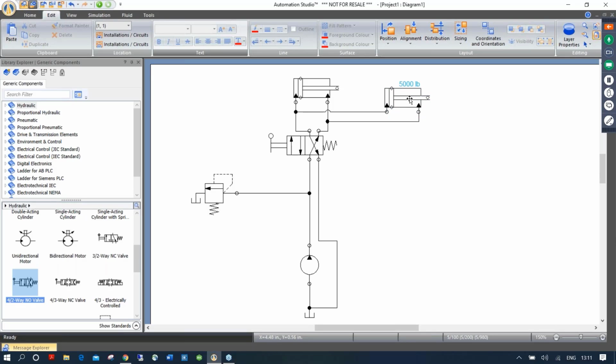We inserted a 40-degree angle in the properties, but the cylinder remains flat. Because since we follow all the ISO standards, we don't turn components on drawing, but for teaching purposes, you can click on the component, go to position, rotation, change the rotation point, and I can actually click on the corner here and just rotate my cylinder like that. The purpose of putting a weight and an angle is to measure the pressure required to lift this.